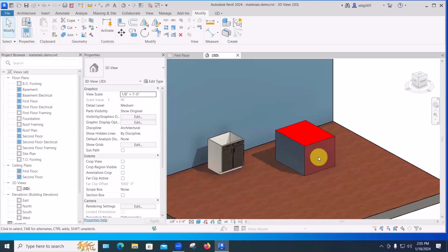But if we then move grass.jpg somewhere else on the hard disk, or erase it or rename it, Revit won't be able to find it and will just render that part of the model as gray. So it's really important to have, on the computer you're working and rendering on, a dedicated folder for images that you're using in your Revit model.